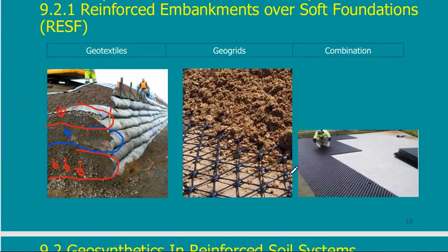So this is the geotextile, this is the geogrid, and here a combination. Maybe I would put both. Why would I put both? Because each type of these has a benefit.